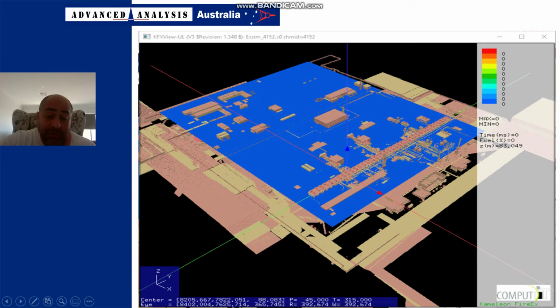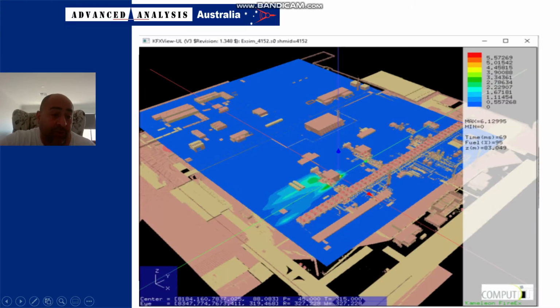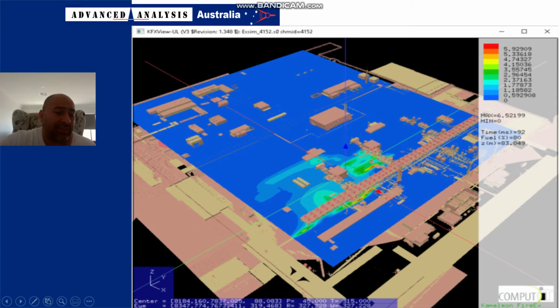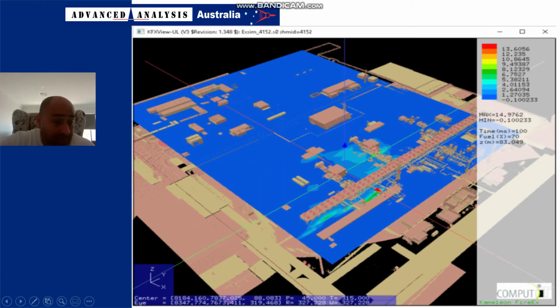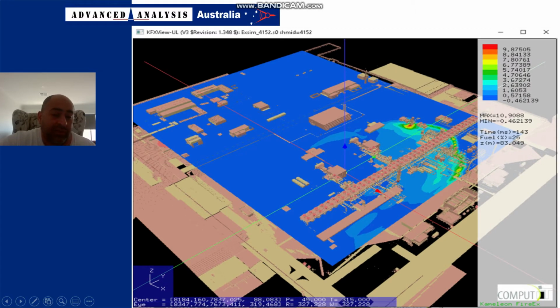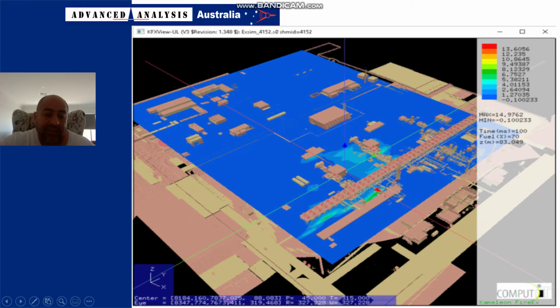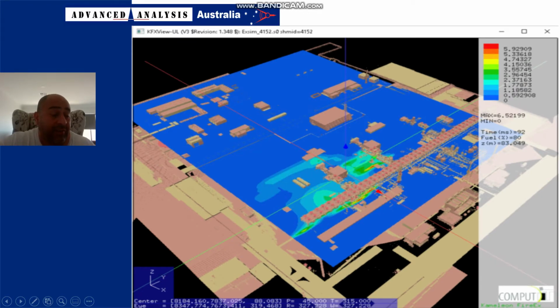Let's talk about gas explosions. In the past, to do a gas explosion using CFD, you basically had to model the site in 3 dimensions. That's expensive, it's time-consuming, it may not always be possible, and in fact, the end result of 3D CFD used for explosions has a large uncertainty. This is something that we don't discuss too often, but there's a 30-50%, even order of magnitude, sometimes, uncertainty for state-of-the-art CFD.